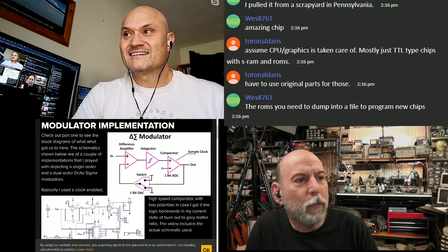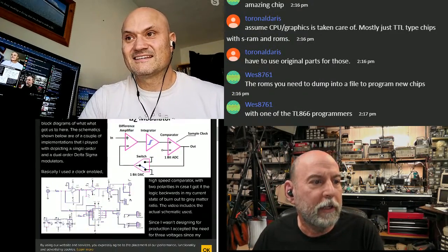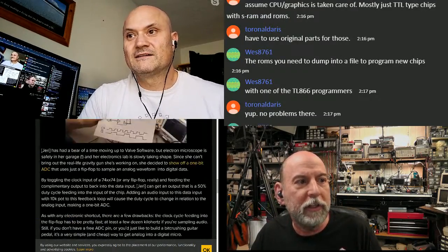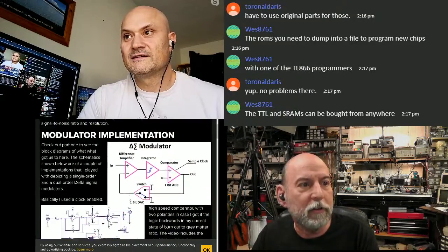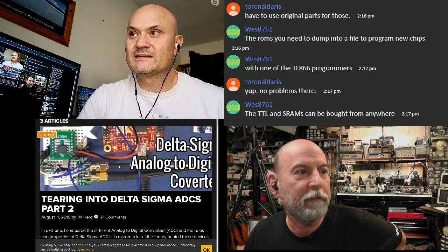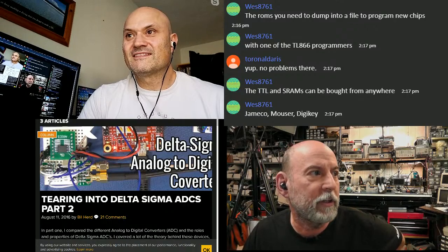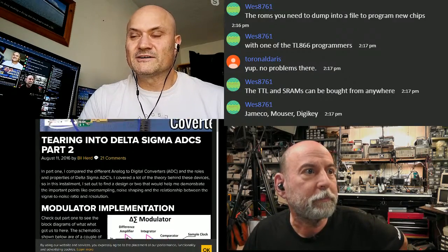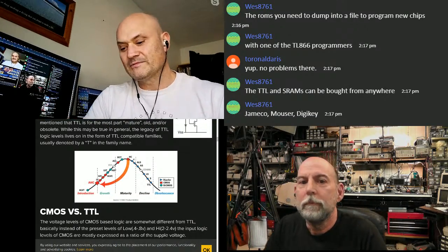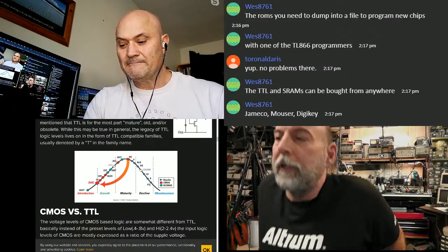Yeah. So here's a 1-bit comparator used to make a delta sigma modulator, and I actually showed it on the scope, where the scope would do the actual averaging, and you could see the signal out of a single bit comparator. I forgot everything that's in this article, so I'd have to read it again. But I talk about successive approximation and everything else. The cool thing about the delta sigma process is you can use it for A to D and D to A, like you can with successive approximation. You can kill two birds with one stone. And do digital filtering. Yeah.